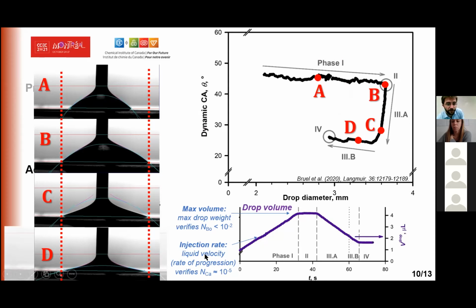That's something you can really see when you stop your movements. If I had viscous forces, then when I stop my injection, I will still see a small change afterwards, as the viscous forces keep influencing my contact angle. So if, when I stop, it stops, it means that I have done my job of calibration well. I have chosen the right rate of injection.